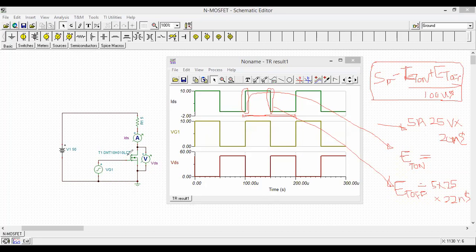The higher the frequency, the more losses you have, and the device heats up faster. So the total loss of the MOSFET is this dynamic loss plus this static loss. Static loss is when you are driving this current, 10 amp, into this voltage drop across here, maybe a very low value, 65 millivolts or something.